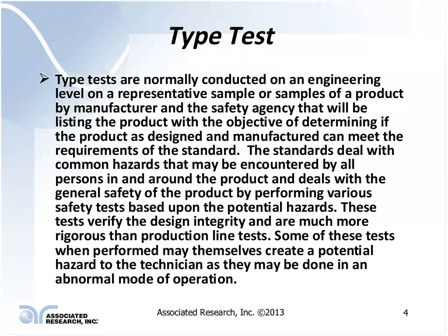If the product is submitted to some type of a surge voltage test on the input, what effect could that have on the product itself? If there's an overload, if your product is designed to have a fan and the fan fails, does it create an overheat condition? So these are all different types of tests that are conducted as a type test to evaluate the design itself.